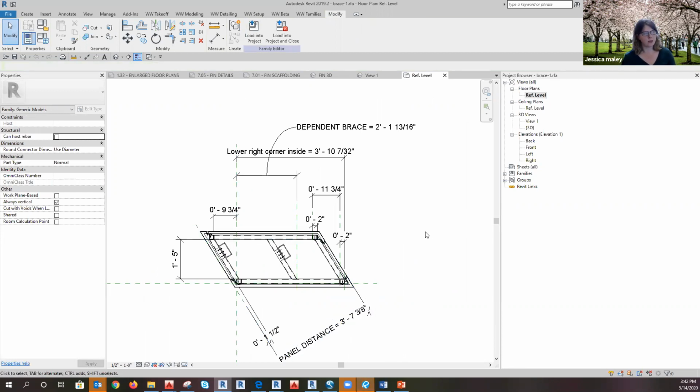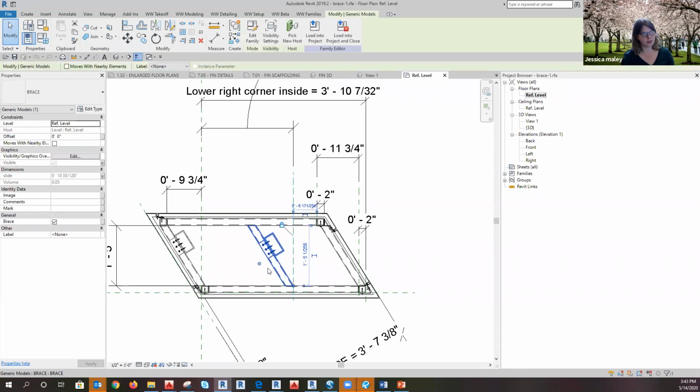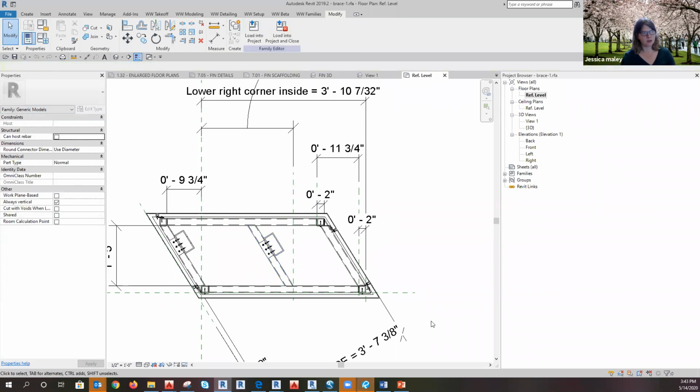So once we built this and put it in our model, we could use the toggles or the values to move this brace in and out and to move this brace in and out. And then the other thing with this brace is it didn't occur everywhere. So it additionally had a visibility parameter just to turn it on and off. So first we made just the 3D model, then we had to make details.